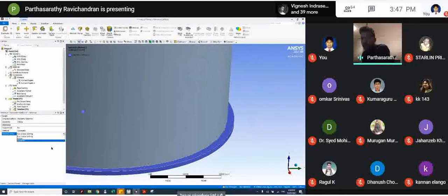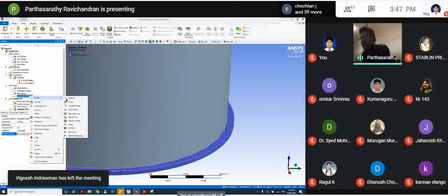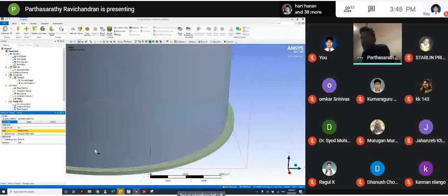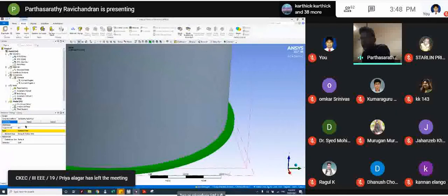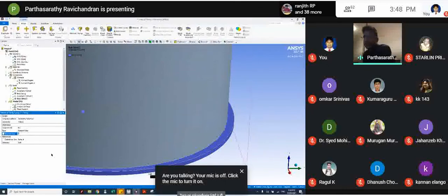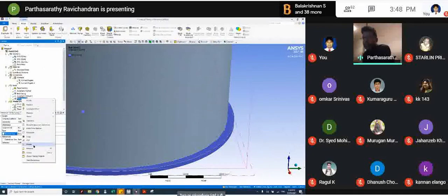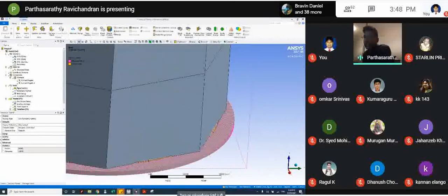How do you want to enforce the element type? Then, again with the method, you can insert the sizing, define this is my geometry of interest, and apply. By default, it has its own sizing. I would suggest that you have at least 2 or 3 elements through the thickness of the body of interest. So here I enforced a size of 30, and then it was able to quickly mesh the body. So let me delete it and show you how this gets done.